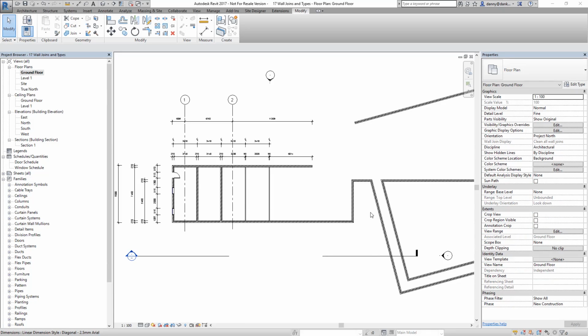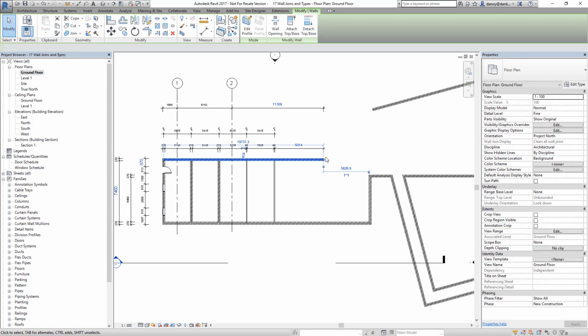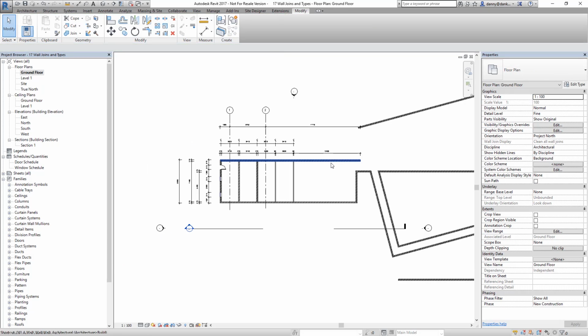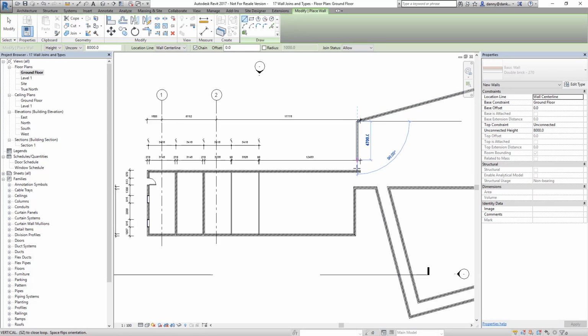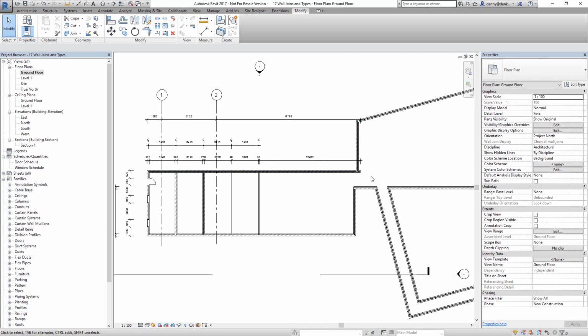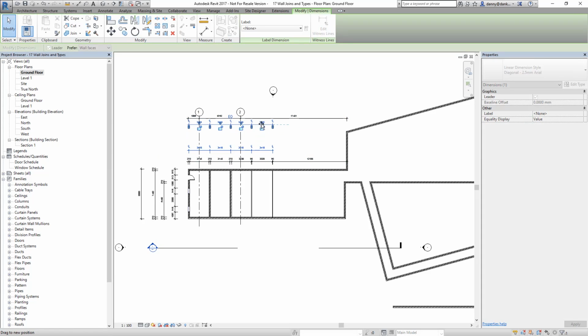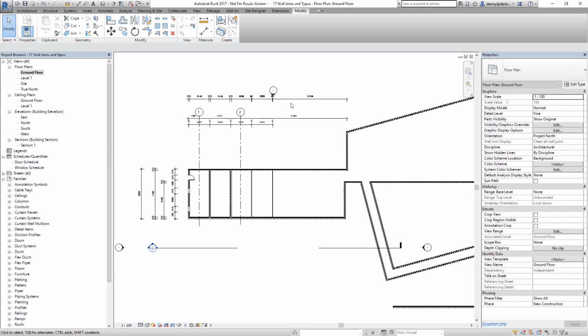In this tutorial, I'm going to show you how to customize walls. Let's just say I'm going to extend this wall to here, and I'm going to create another wall in through here, just for argument's sake, and trim these together. You can see the dimension automatically moved, which is great. Just move these dimensions up and out of the way.